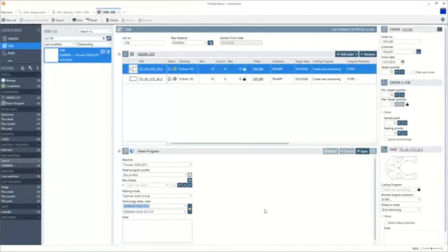My profile is going to have information like my sheet margins, my web width between my parts, my sequencing direction, my type of movement or traversing between parts and contours, the nesting engines and algorithms I want to use, sheet cut parameters, microjoint or tabbing parameters. There's well over 100 parameters in there, I would say, for those profiles.